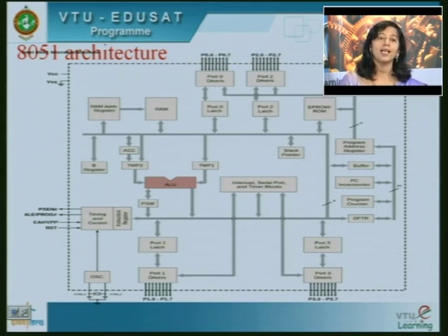The other operand can sometimes be in the B register. Usually for multiply and divide instructions we need this register, but almost every operation, whether it is add, multiply, and, or XOR, whatever, one operand is always in the A register or the accumulator.